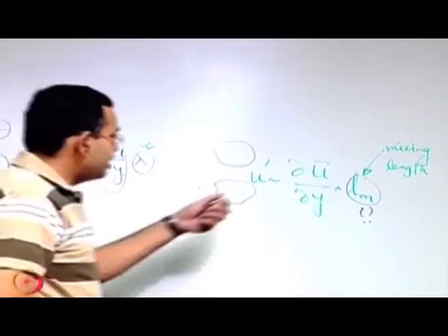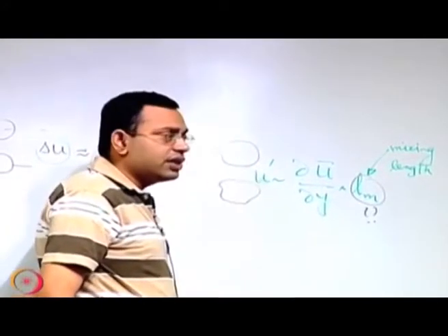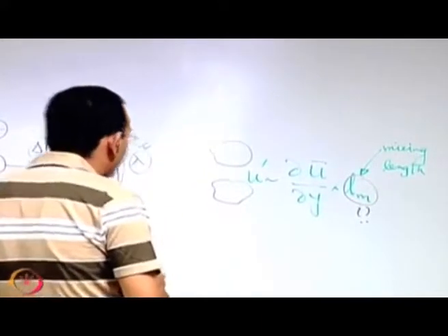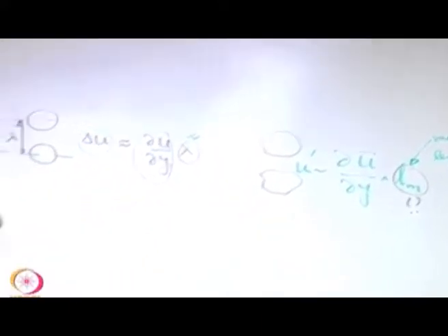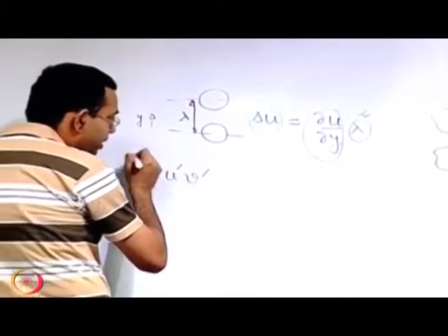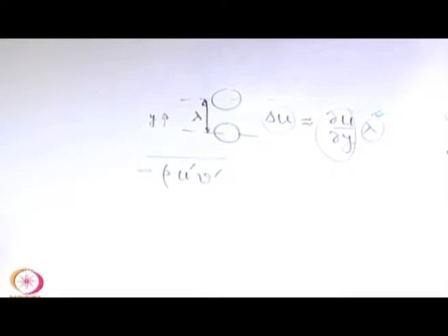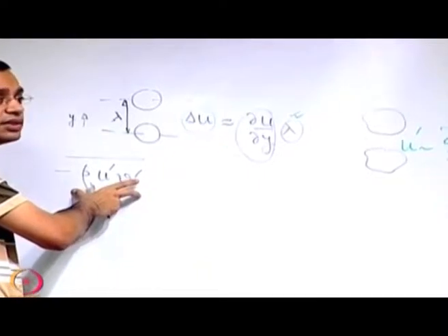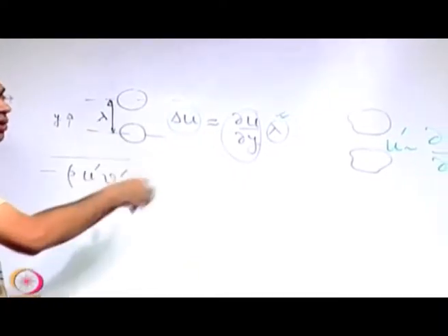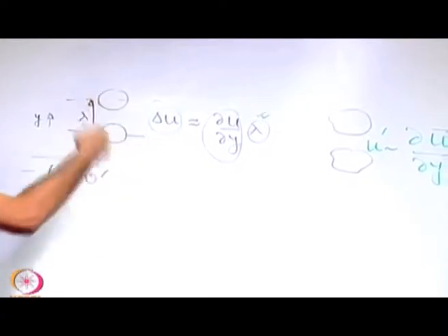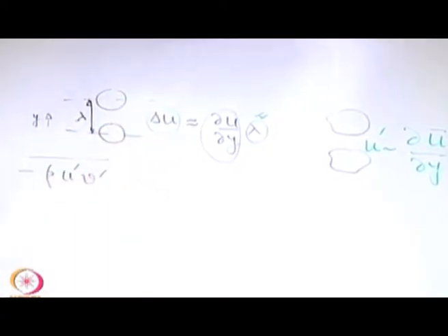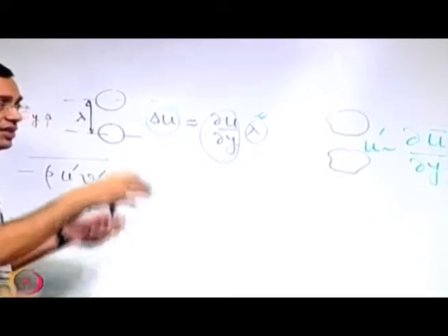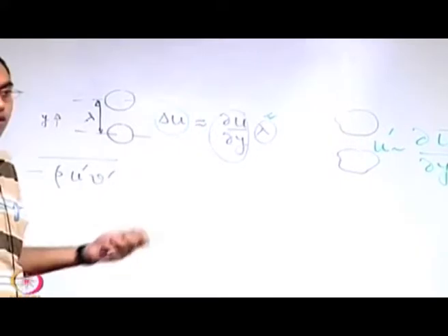Now why was this type of quantification important? Because eventually Prandtl wanted to model the Reynolds stress term, that is minus rho u prime v prime as an example, with an average. So we could see that this is an extra term of the same dimension as that of stress, which came into the picture because of the Reynolds averaging of the Navier-Stokes equations. And since these are not known quantities, it gives rise to a tensor with 6 unknowns.